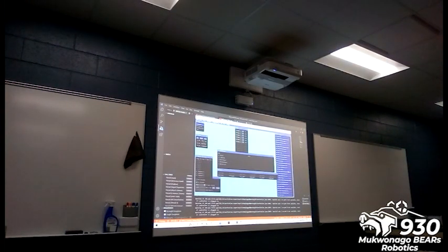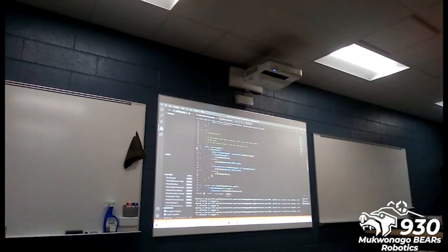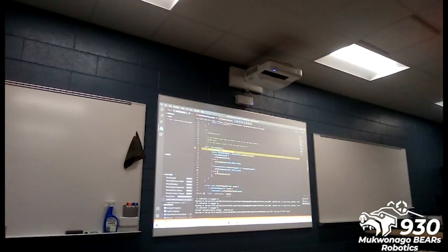So the motors that would be affected by this would be 13 and 14, which you can find in your other devices tab here. And you can open those up, and it'll give you some information about the current state of the motor. So here we can go to our code and place a breakpoint like that. And from there we can turn our simulation onto teleoperated so that our code is running. And you can see our breakpoint will trigger.